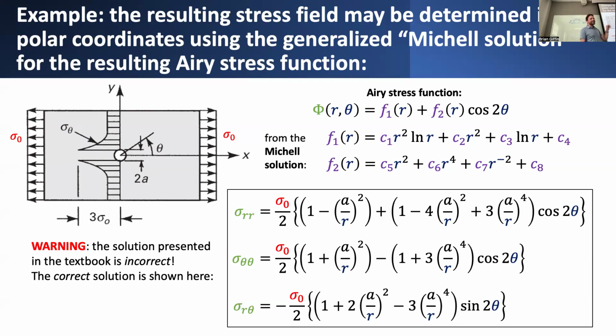We can come up with a conclusion of how the stress field locally changes in the vicinity of this hole. So just to give you broad strokes of what the solution procedure would look like if you had to do it, not that you would. The idea is we would use our polar coordinate form of our equations of elasticity. So rather than doing everything in terms of Cartesian coordinates, with equilibrium and everything defined relative to an XY coordinate frame, it actually ends up being convenient for this problem, if you have a truly circular hole cut into this member, to do everything in terms of polar coordinates.